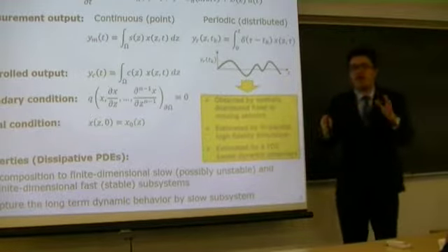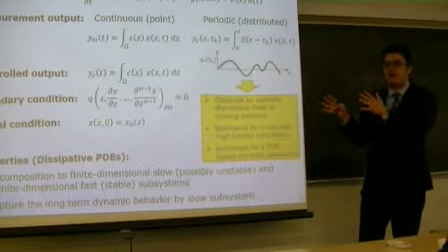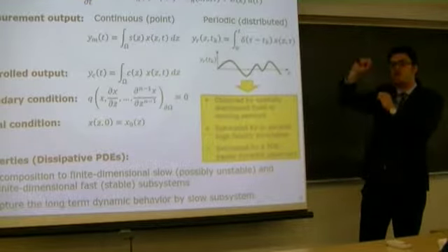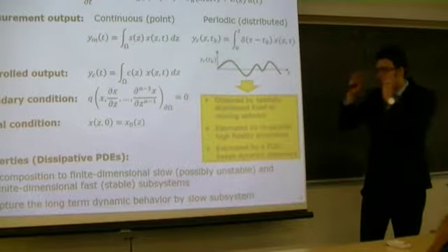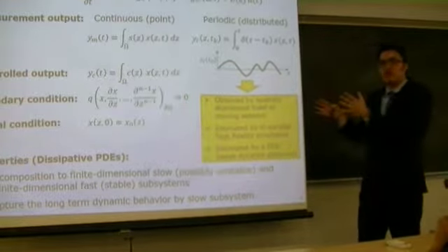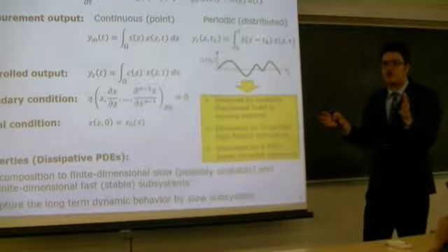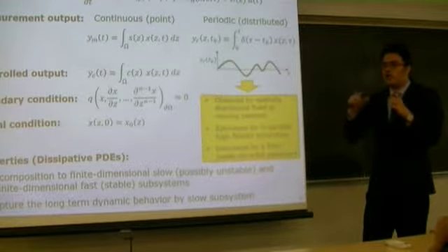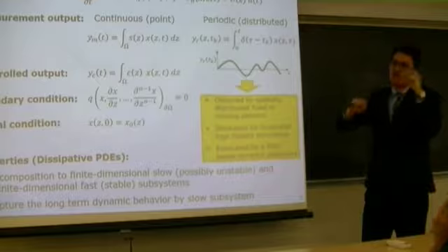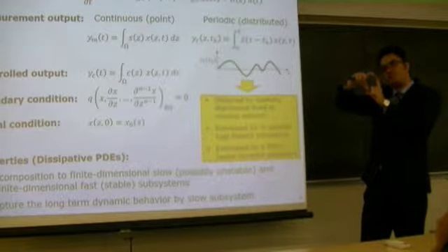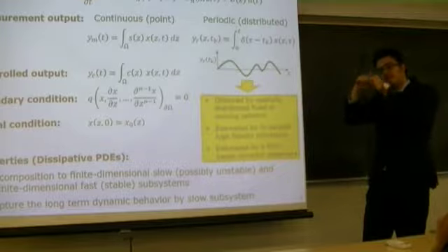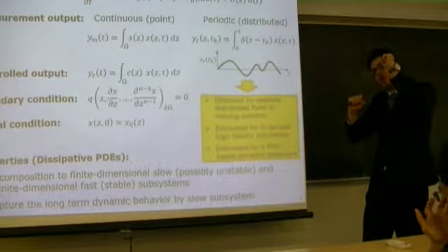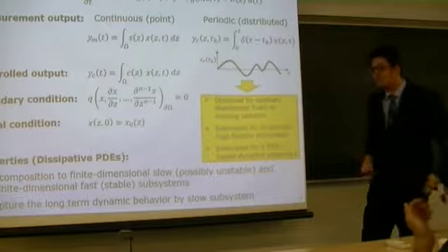Okay, so I will show you a simple example of how you could identify those modes and use the important modes for the control design. But specifically for dissipative or parabolic partial differential equations, when you solve the eigenvalue problem, you could find a big separation between the values of the eigenvalues that indicates the separation between the governing subsystems.